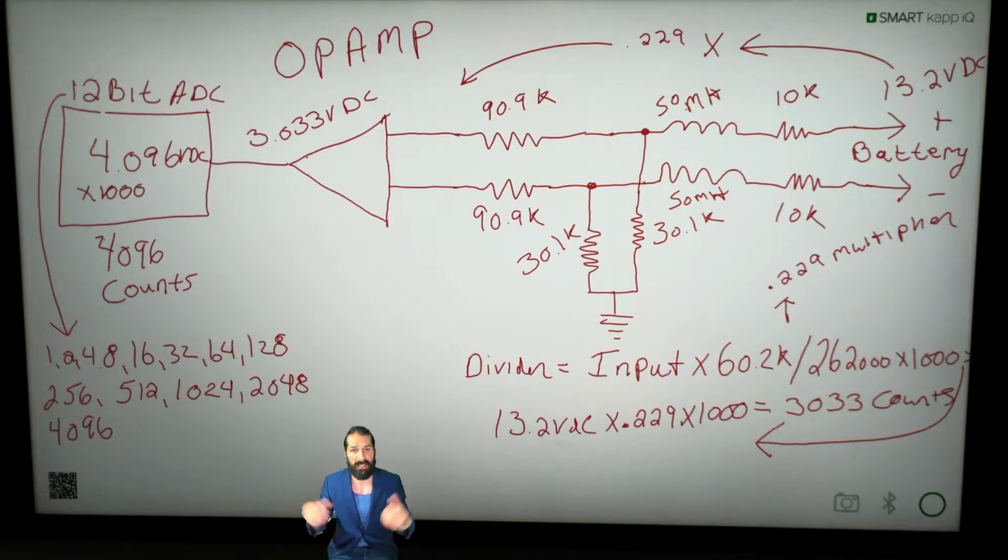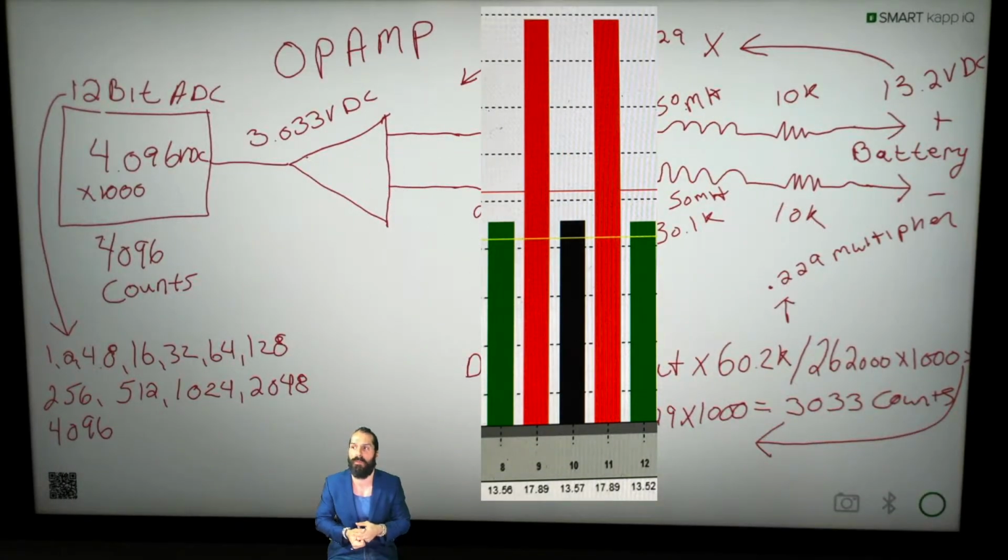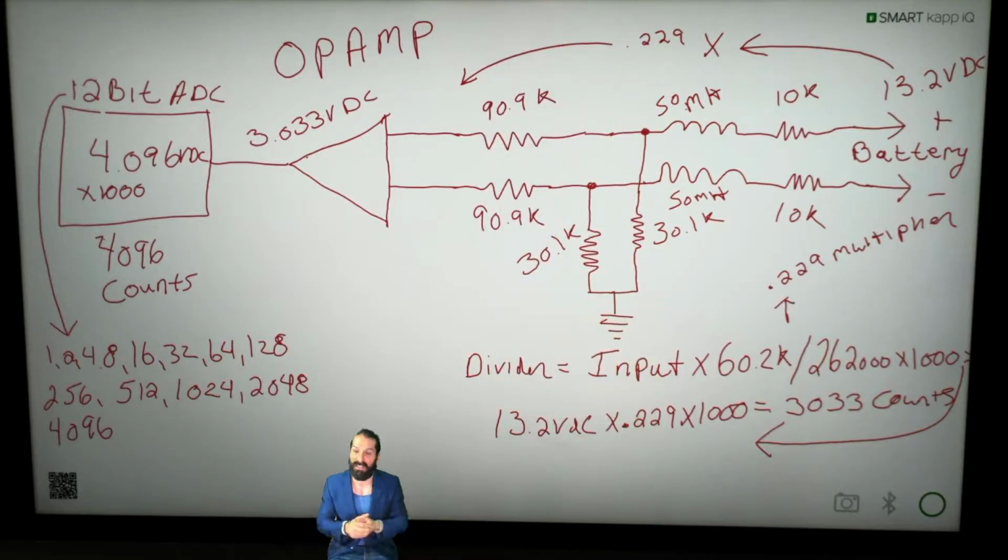And let's say some of the acid eats through that butt splice, and now that 10K resistance has gone up to 20K or 30K. Well, how does that impact the monitoring system? What you're going to see is a voltage drop across that connection, and the system will basically shift up like this. Now, I'll put an image of that up here if I can find one from one of our technical reports. I'm going to dive into this in detail in an Excel spreadsheet that I designed for you to help you understand why this is important.